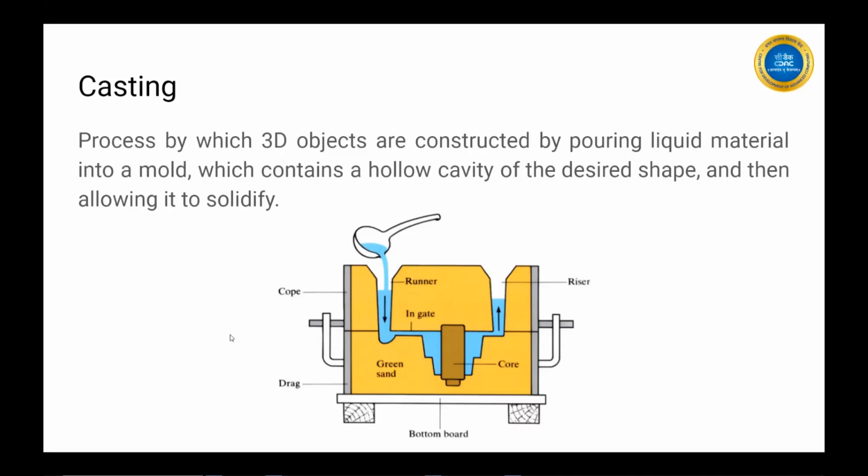But the initial cost involved in casting or molding is too high because we have to make a tool out of subtractive manufacturing, a tool and die has to be made. This is actually the die in which the cavity will be there, and to make that die, even for a small water bottle, the tooling cost is close to 2 to 3 lakh.